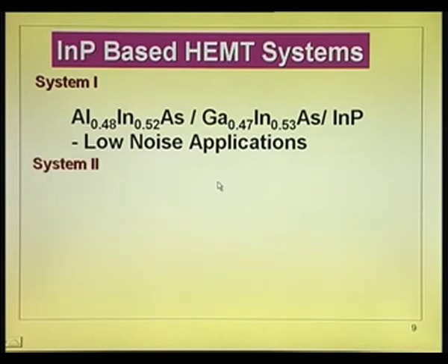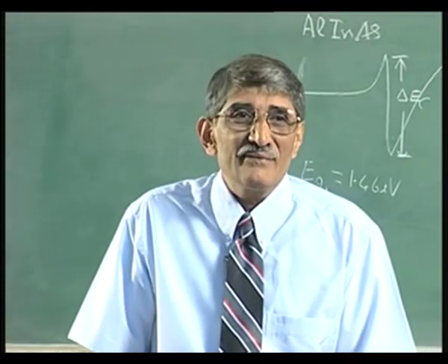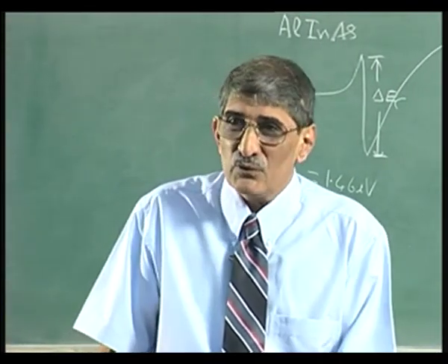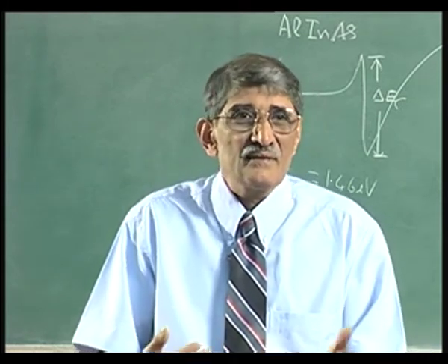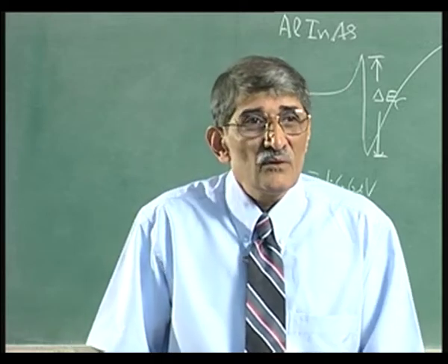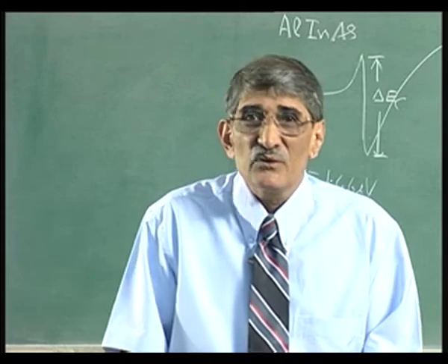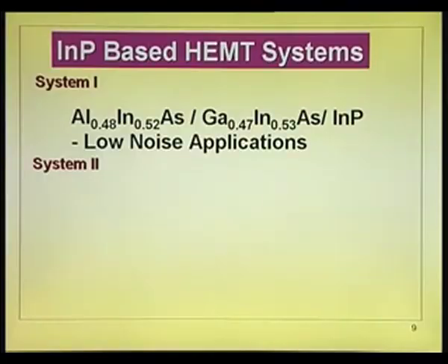Another type of HEMT, I am just projecting it to you, because you have opened up a real wide variety of devices that you can get when you use this type of materials. You make slight changes in the arrangement, you get different performance. Depending upon your requirement, you can choose those types of devices. So, low noise is this one, but you will see that this type of device gives low breakdown voltage, very small, less than 5 volts. So, when you get certain benefits, you lose in others, so you may not be able to go to higher powers.